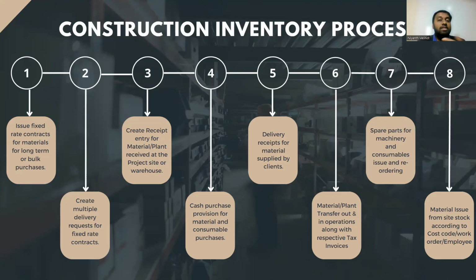The next one will be the delivery receipts for the material. The first one is the entry receipt. Fifth one is the delivery receipt. So delivery receipts means this will be provided officially by the provider or the vendor himself. This is where they will be giving the quantity, the specification of the material, the test results of the material as well. Most of the materials would have to go through a number of tests in the manufacturing plant before being delivered to the site, and that document is called MTC, that means Manufacturer's Test Certificate. So that also will be given with the delivery receipt.